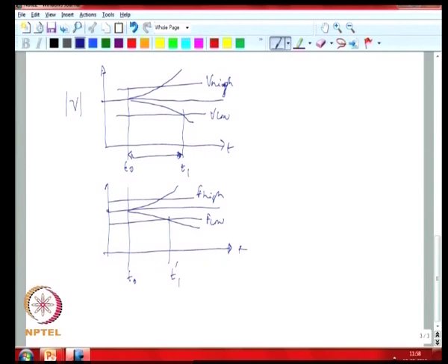So the DG has to disconnect, and this duration is typically less than 2 seconds, because you want to detect that an unintentional island has occurred before the upstream recloser recloses. So you want this detection to happen fairly quickly.